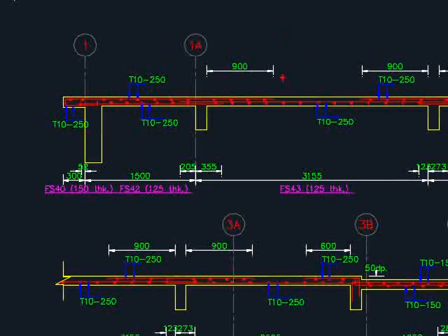However, for this slab, which is adjacent to this, now the main and the secondary reinforcement bar swap, which in this case, you will need to provide lapping in terms of the reinforcements, and the positions where the reinforcement bar can stop need to be clearly indicated.